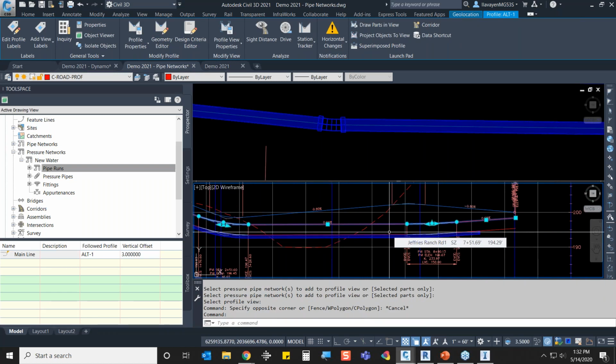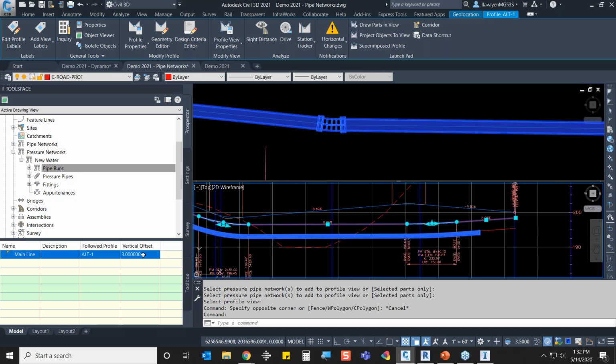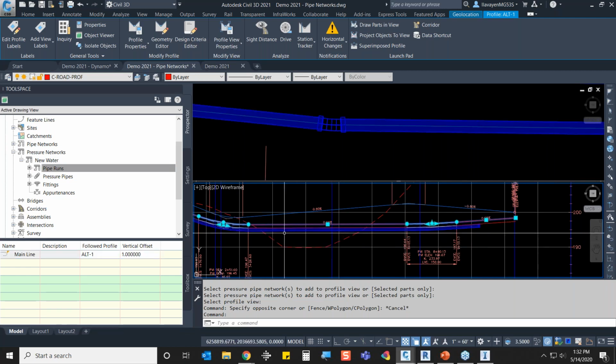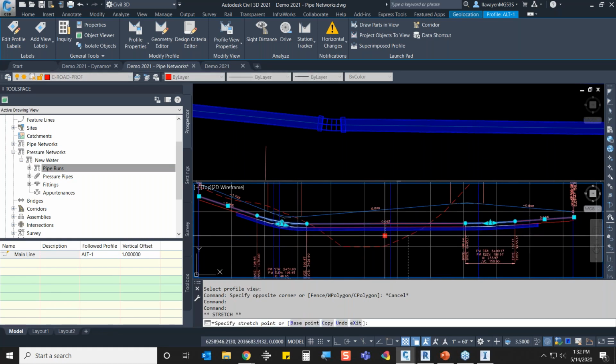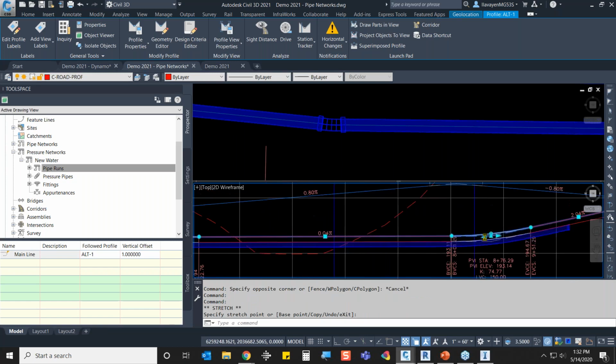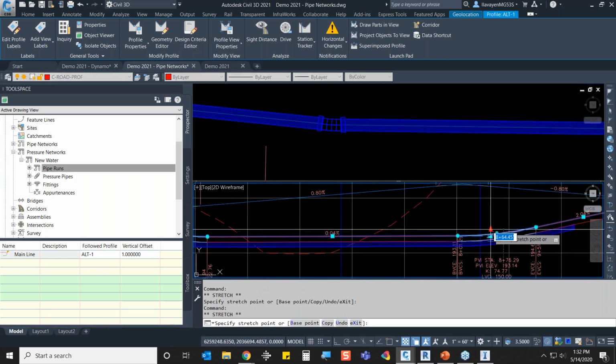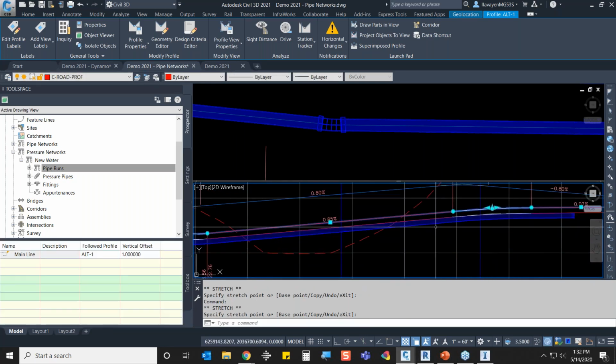Maybe I created my own minimum depth. I sketched in where I want that network to be at. Hey, what if I wanted to change that depth? Right now it's at 3 feet. Let's go ahead and have it be at 1 foot underneath my alternate. Boom, it updates immediately there. Or if I change my vertical design, what it's supposed to be following, let's drop it, or let's raise it, or let's lower it. It's dynamic, it's immediate, guys. It's just happening. Freaking love it.